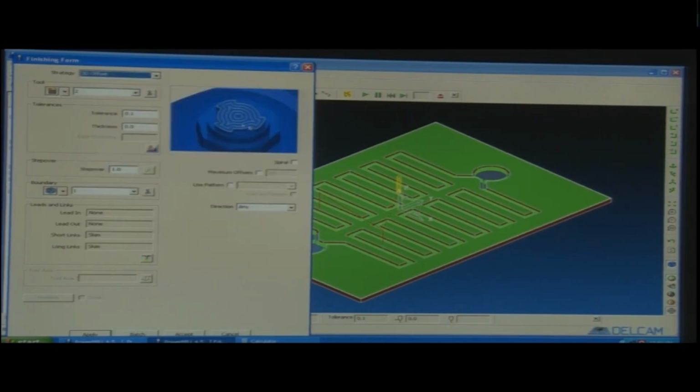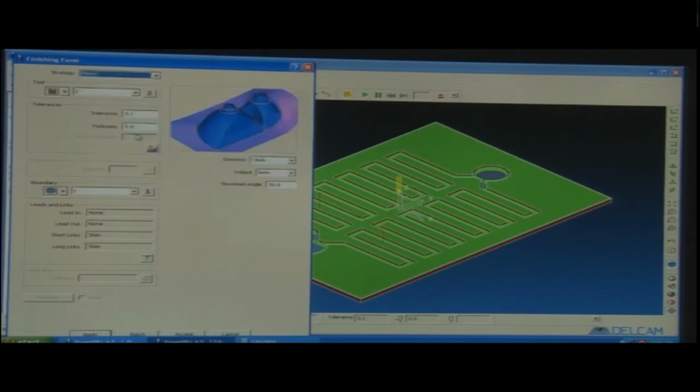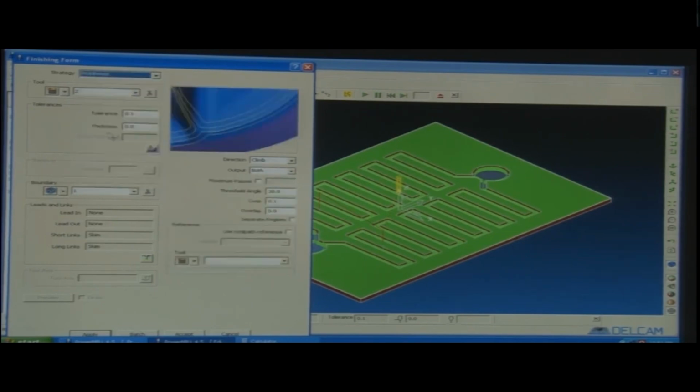Okay, what is 3D offset? 3D offset is just for the top profile. Then pencil is just for the corners, actually the edges of the workpiece. There are sharp edges there. So, those edges are now worked on using this pencil command. In manufacturing, it is generally for some fillet radius or something, some fillets are there. When sharp corners are required, then the pencil command is used.